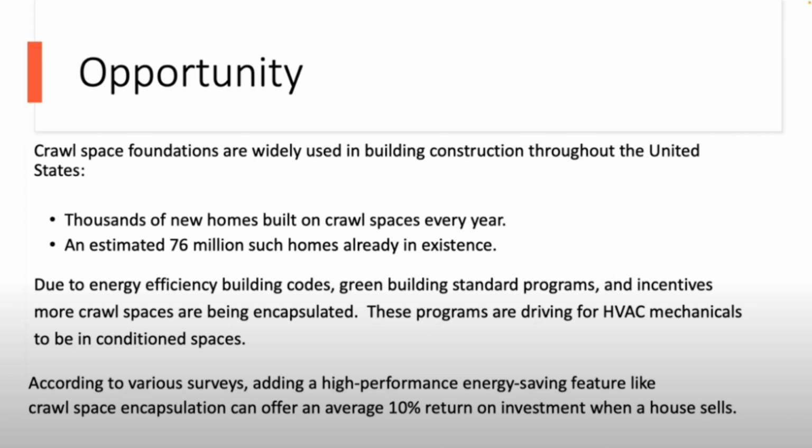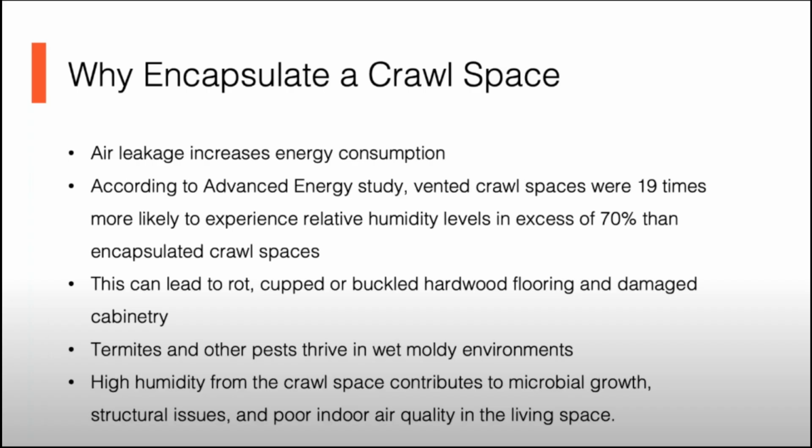Due to energy efficiency building codes, green building standard programs, and incentives, more crawlspaces are being encapsulated. These programs are driving for HVAC mechanicals to be in conditioned spaces. According to various surveys, adding a high-performance energy-saving feature like crawlspace encapsulation can offer an average 10% return on investment when a house sells. I believe this is important to note because encapsulating a crawlspace is a large, labor-intensive job and does come with a price tag. So why do we encapsulate crawlspaces?